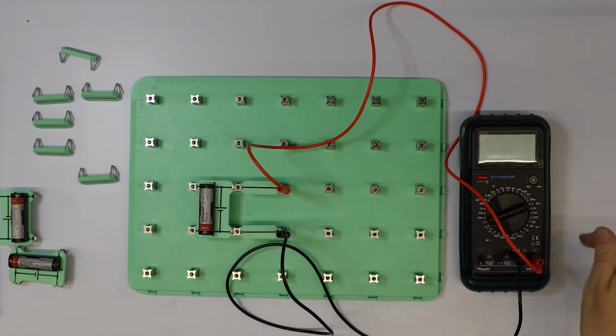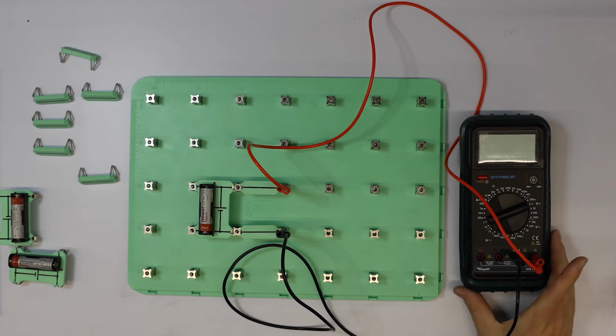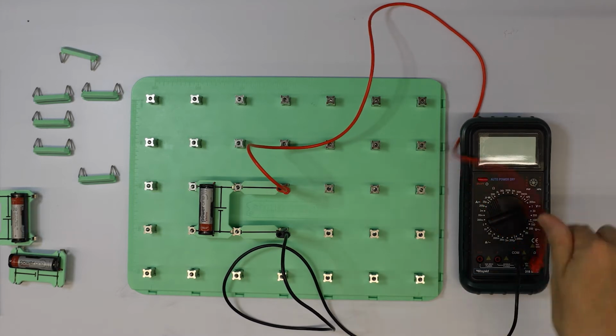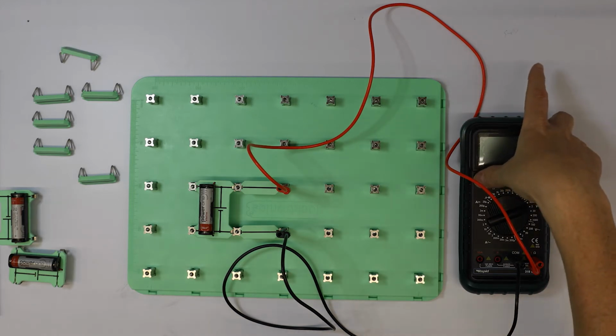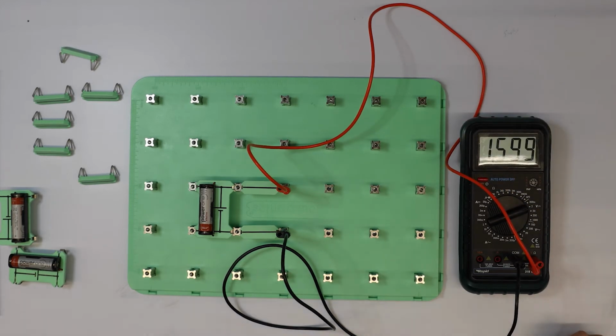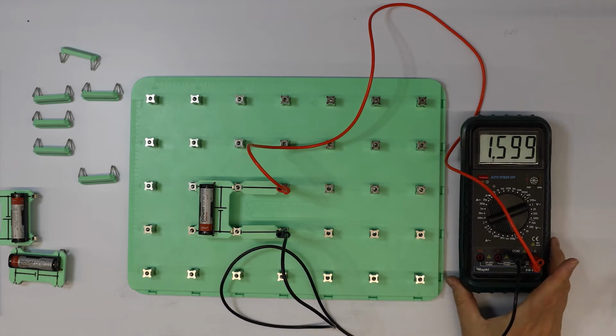The good thing about using a multimeter for voltage measurement is it's very difficult to damage the multimeter, because it has such a high internal resistance that it can't be easily damaged by the high currents you could get from a short circuit or that kind of thing. So I'm fairly safe, so I'm going to turn that on and see what I get. And so you can see the reading here. That's actually measuring 1.599 volts. So what I'm measuring here is a very healthy battery. It's fully charged at 1.59.